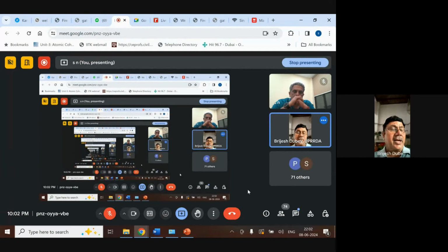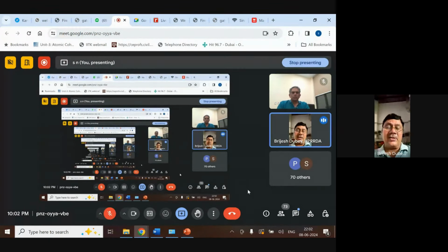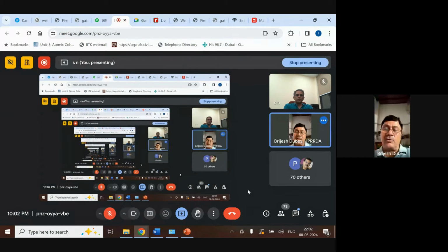This is one. Number two, there was a question regarding the availability of the crust. What I am saying is on the basis of the experience in UP, wherever there is a crust more than required, we have provided soil or earth, or we can say fines, above the granular materials, and we have tried to keep the ratio 30 to 70% fines and granular, and vice versa. Somewhere we have got very little granular material.